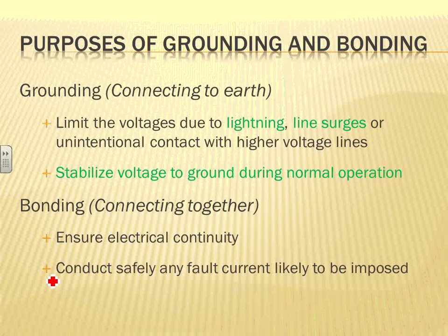If you have a grounded system, guys, the advantage is you almost always have two voltages, 277/480 and 120/240. So you have two levels to work with. That's a big advantage. Lights at 277, air handling unit at 480. Okay, so that's check. Second, it stabilizes the voltage to the ground.